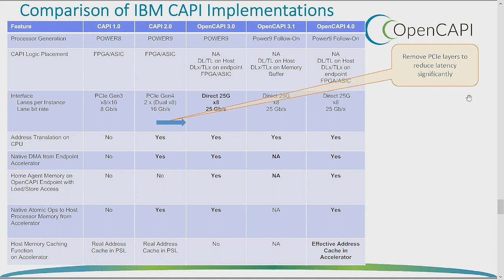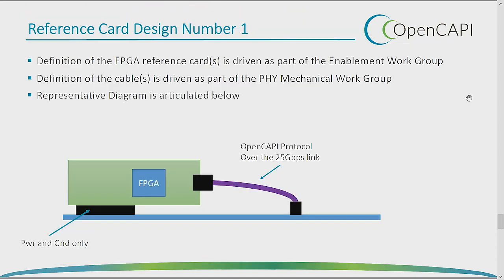We have like 400 gigabytes per second of sustained bandwidth. So a massive bump in bandwidth to support accelerators, high-performance computing. And this is something where we'd like to see other vendors pick this up, right? Or even accelerators, right? If you want to put a lot of memory behind an accelerator, use this OpenCAPI memory interface. So that's what we have on the short list.